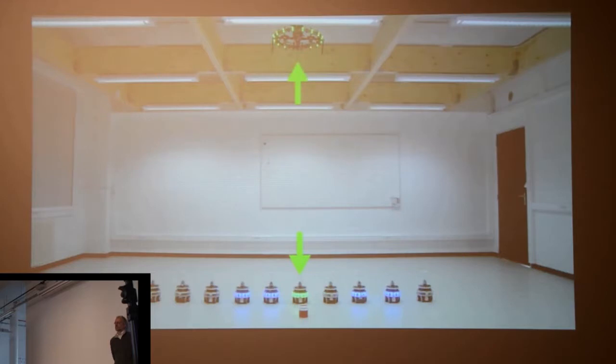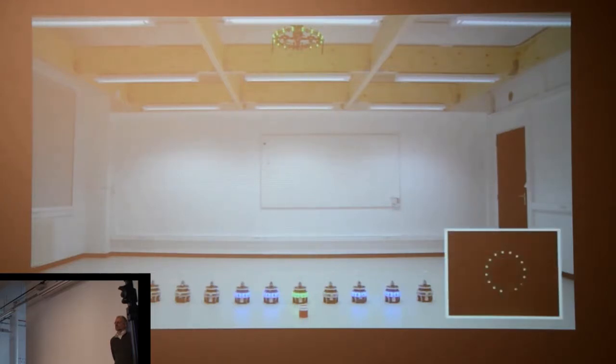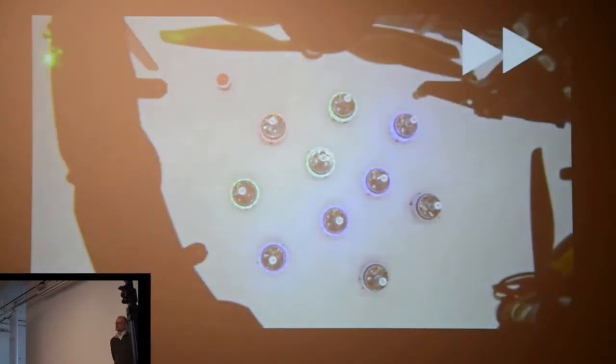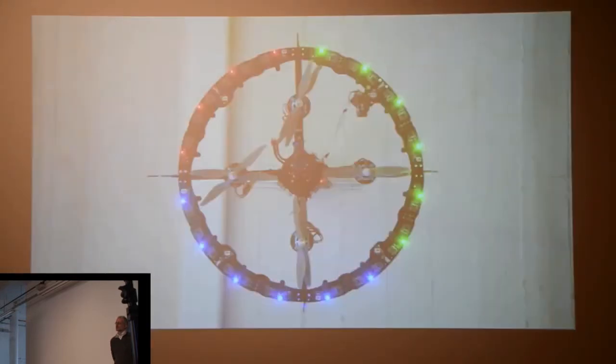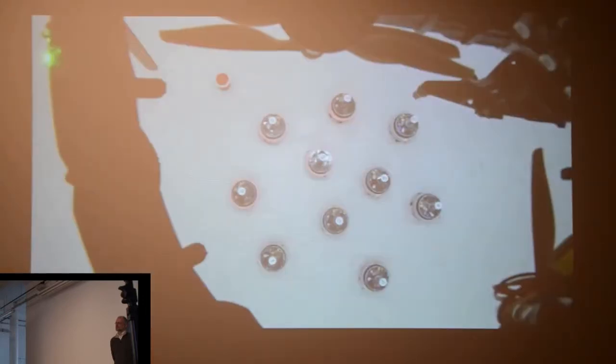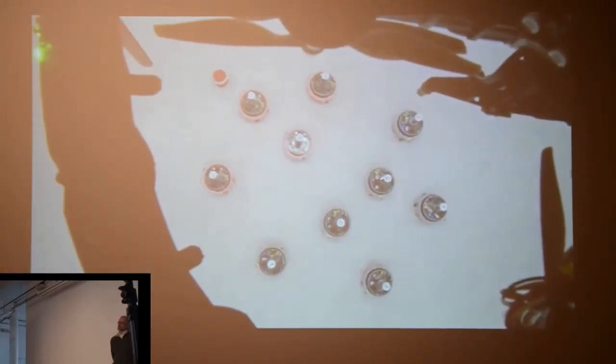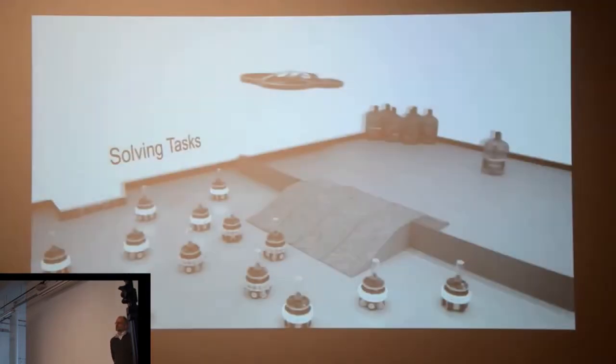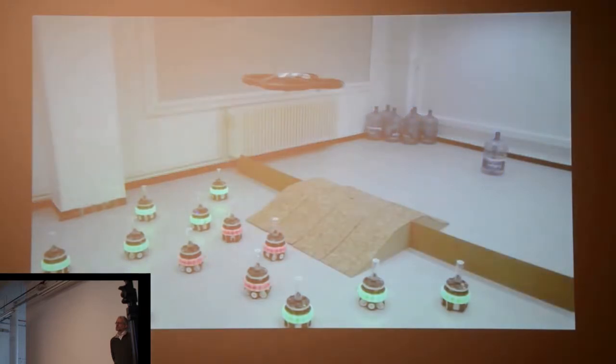In a series of elimination steps, each ground-based robot independently displays a sequence of randomly selected colours. At each step, the flying robot matches the colour of the target robot. Whenever a robot on the ground sees that its own colour doesn't match the flying robot's colour, it eliminates itself. The process continues until only the targeted robot is left. An extended version of this method allows adjacent groups of robots to be selected and then given movement and morphology formation instructions.